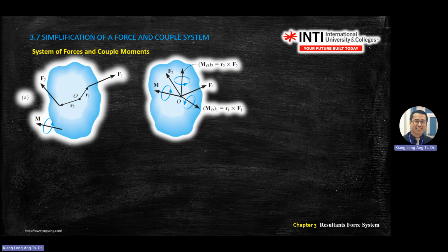Yeah. So this means you simplified the diagram when you solve. So when you solve a more complex system, what you do, you focus on the question. Let's say the question asks you to focus on O. So you move your forces to that location. You know that when you move, you're creating the forces plus the moment. If you shift perpendicular distance to the O, you are creating force and moment. Same with F2. You move F2 to O, you create force F2 and the moment at O. Moment you continue to use.